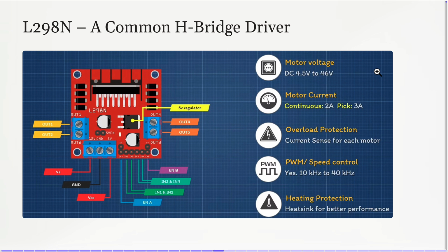If I want to move straight forward, I need to send the same velocity or the same speed to the right motor and the left motor. If they work with the same power, the robot moves forward. Of course, clockwise goes forward and counterclockwise goes backward. Now if I want to rotate, for example, in the right direction, in the clockwise, I will send a smaller speed to the right motor and a higher speed to the left motor.